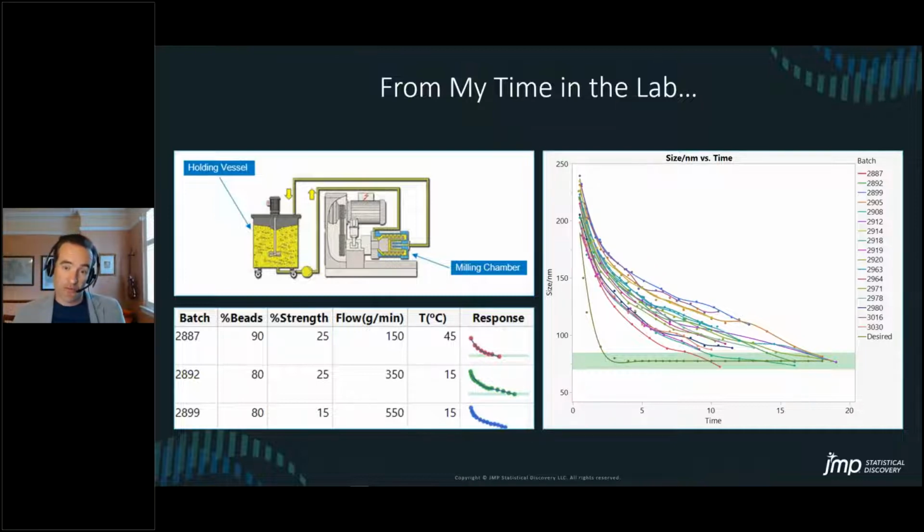What we have is a dispersion of the pigment, dispersed in water with various other additives, and you pump it through this mill, and in the milling chamber there are small, hard beads that are being rotated at 4,000 RPM. They're smashing against each other, they're smashing into the pigment particles, and they're grinding up the pigment particles, and you continually circulate the pigment dispersion through this mill.